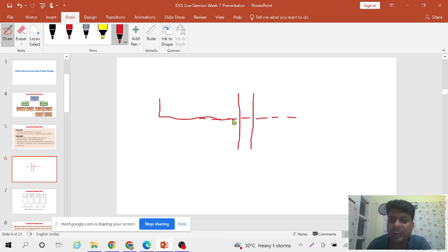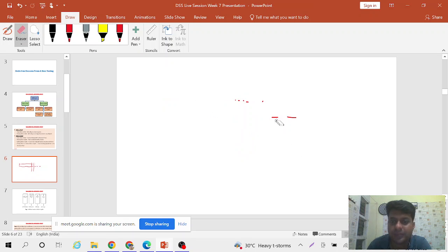And how will failure occur? At the shear planes, at the thread or at the shank portion. See, if this is the shear plane, then the tendency of the bolt will be to get cut into two pieces from the shear plane. Let me draw a neat and clear diagram.